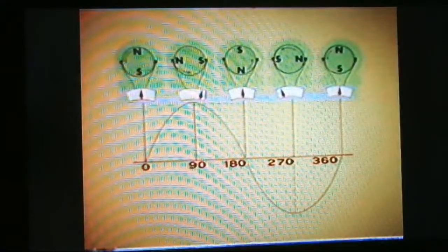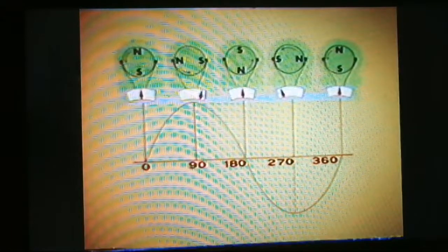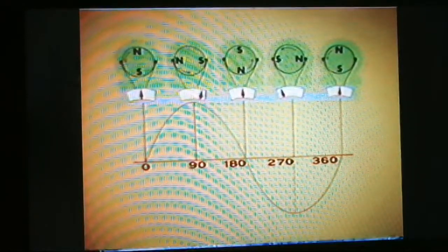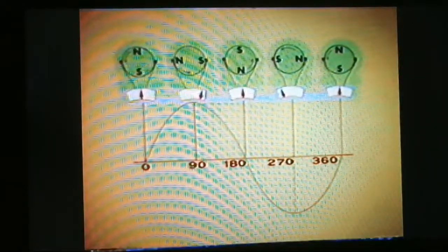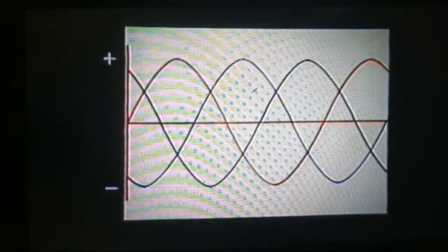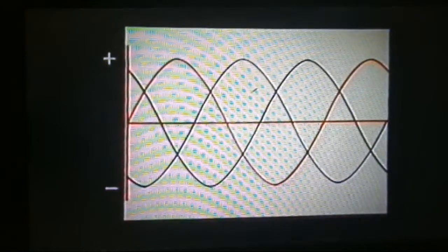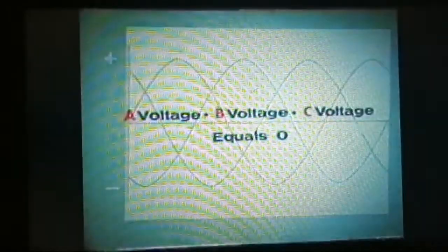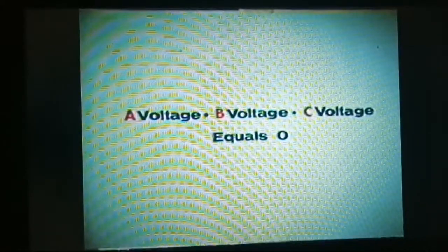Well, for a brief moment here, let's review electrical fundamentals. In an alternating circuit, voltage or pressure rises to a maximum and again decreases. The sine wave. Well, what happens when the three phases are plotted? At any point along the time line, voltages on one side of the zero line will exactly equal the total voltages on the other side. That is, if values are added, the sum of the voltages will always be 0. That is, if the three-phase generator has a properly balanced load.